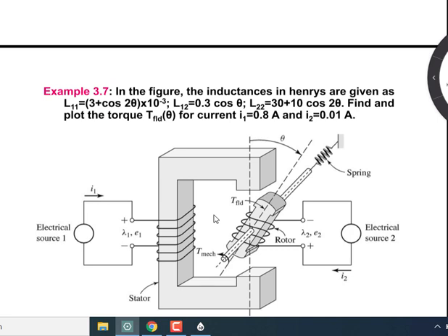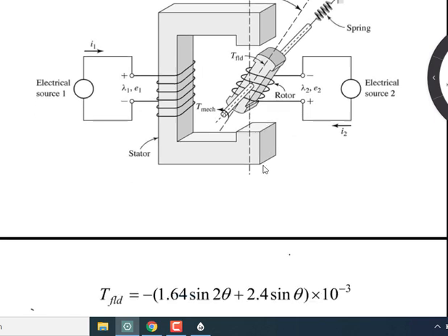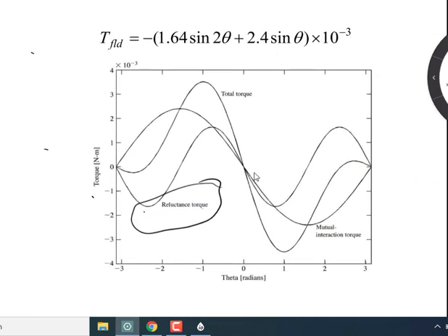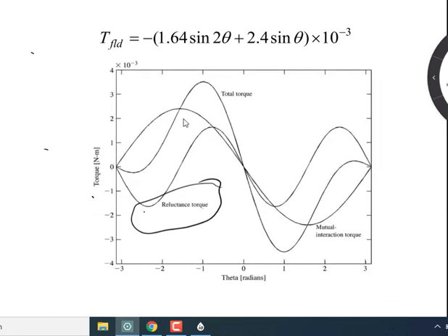However, the salient torque only depends on the inductances that are due to the structure. Had we considered a complete circle, then we would have a different expression of torque, and there would be no theta present in our expression. So in that way, you will get the total torque as a non-sinusoidal periodic curve, right?